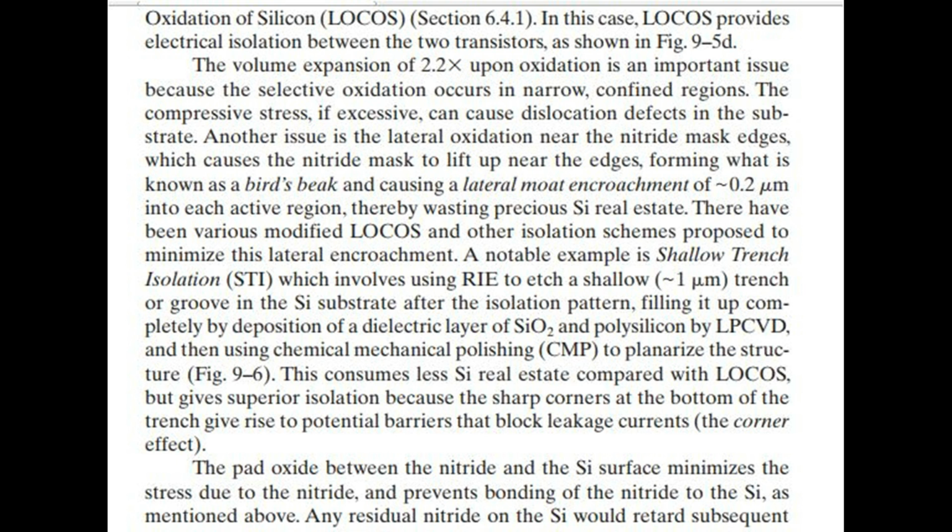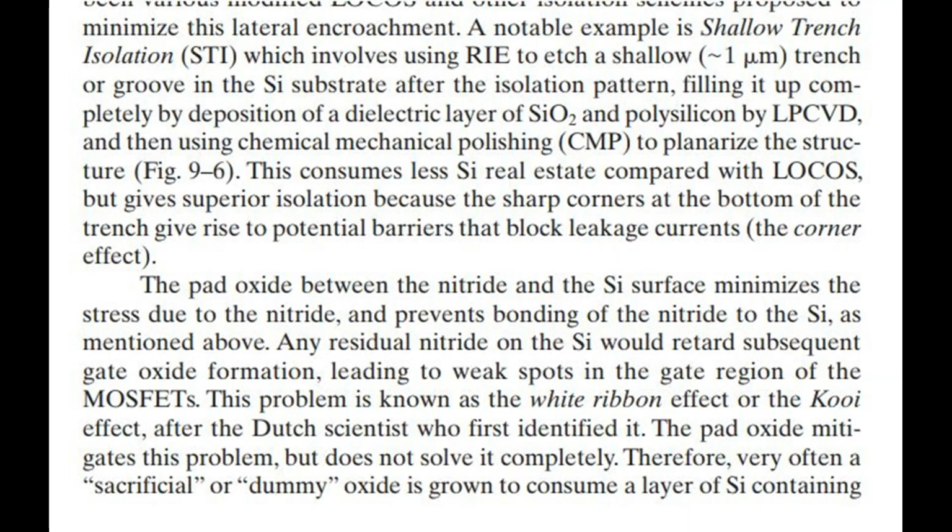The pad oxide between the nitride and the Si surface minimizes the stress due to the nitride, and prevents bonding of the nitride to the silicon, as mentioned above. Any residual nitride on the silicon would retard subsequent gate oxide formation, leading to weak spots in the gate region of the MOSFETs.